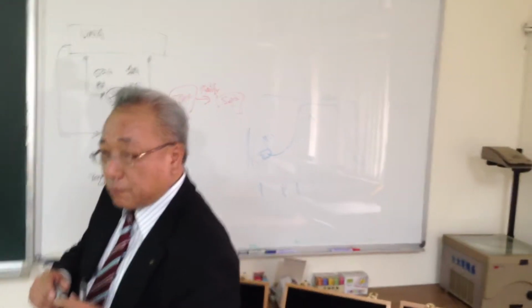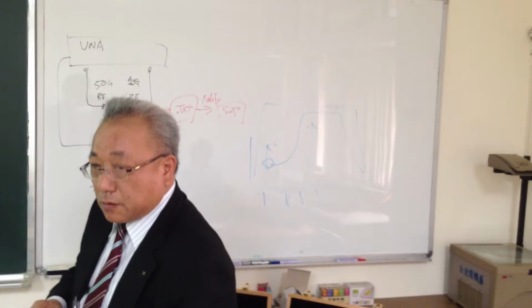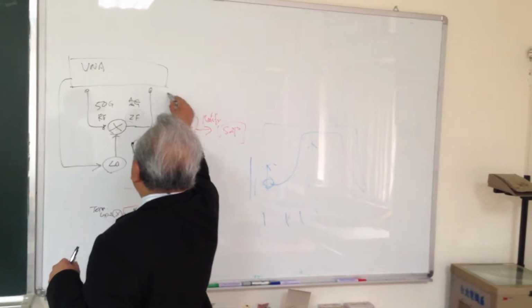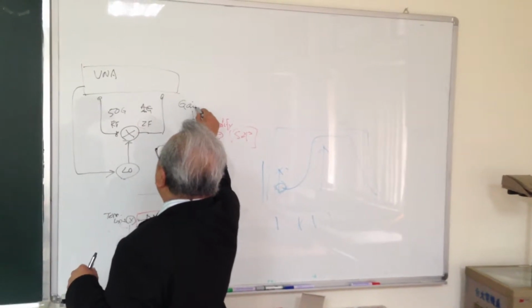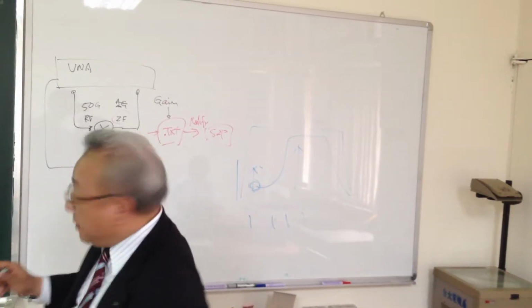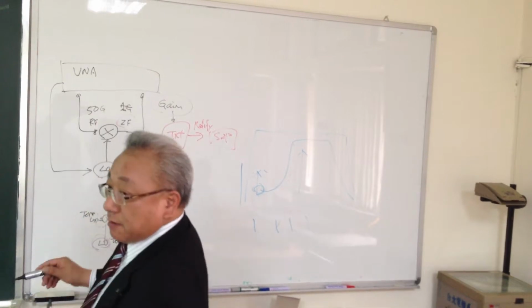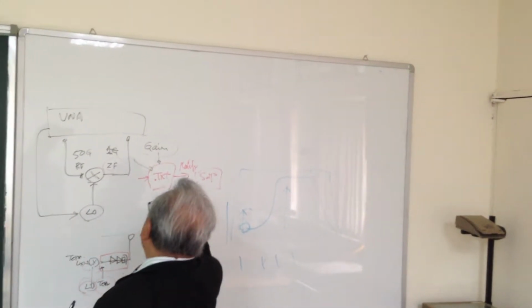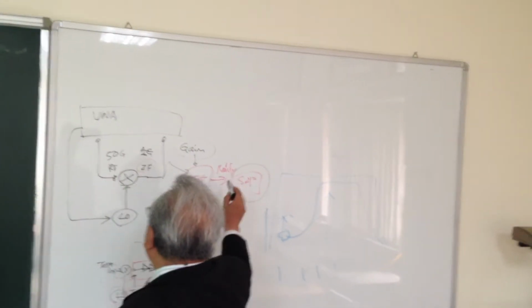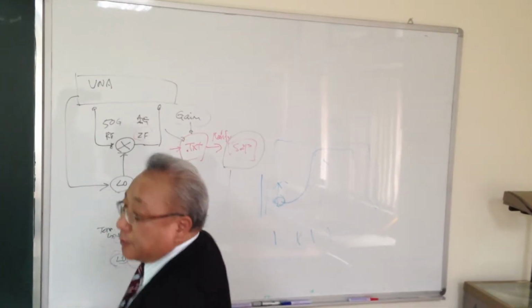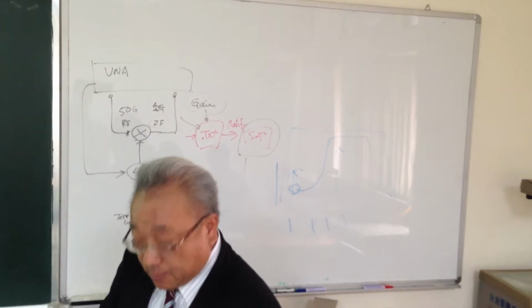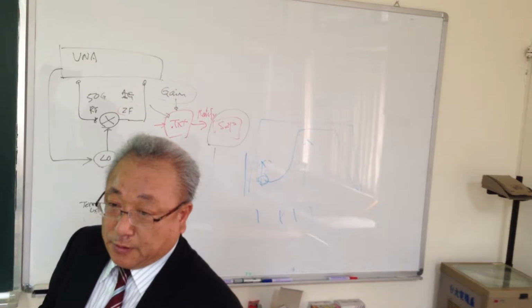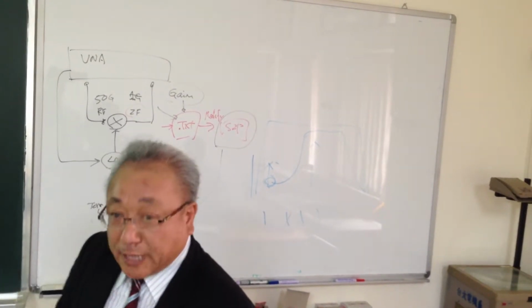Before the noise figure measurement, you generate the TF. That is like the gain of the active mixer. Oh, conversion gain. Yeah, conversion gain. Then save it to the text file first. Then create an S2P file because we have to load it for the calculation of the noise figure. But the conversion gain is only magnitude, only S21.